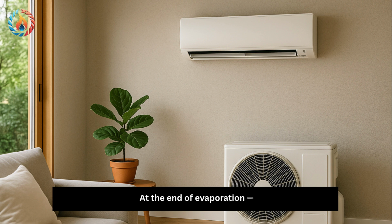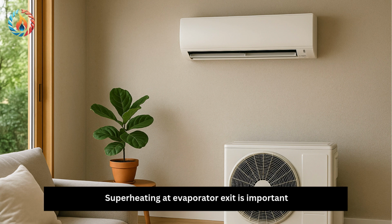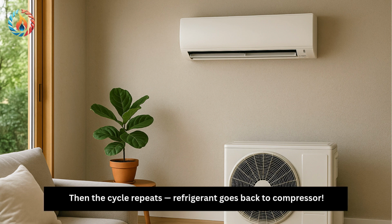At the end of evaporation, refrigerant is low-pressure saturated vapor, or slightly superheated. Superheating at evaporator exit is important. It ensures no liquid refrigerant enters the compressor. Liquid entering the compressor causes serious damage, called liquid slugging. Then the cycle repeats. Refrigerant goes back to the compressor.